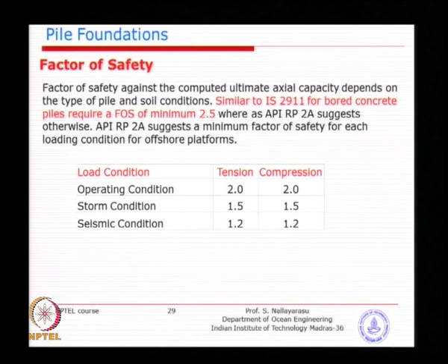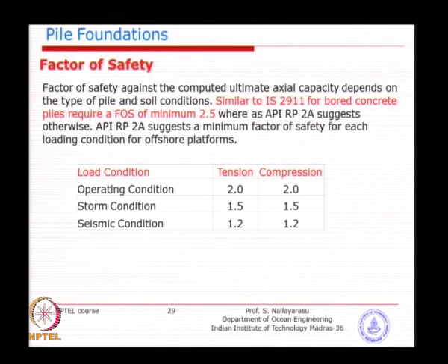So, minimum 2.0, and if you have further uncertainty, you as a designer can increase the factor of safety, but nobody wants to do it unless you have a clear indication from the soil reports that the strength could not be evaluated correctly. In such cases, you may not actually proceed with the project itself, because the risk with the offshore foundation is very high. You go there, you cannot drive, then you have to come back.